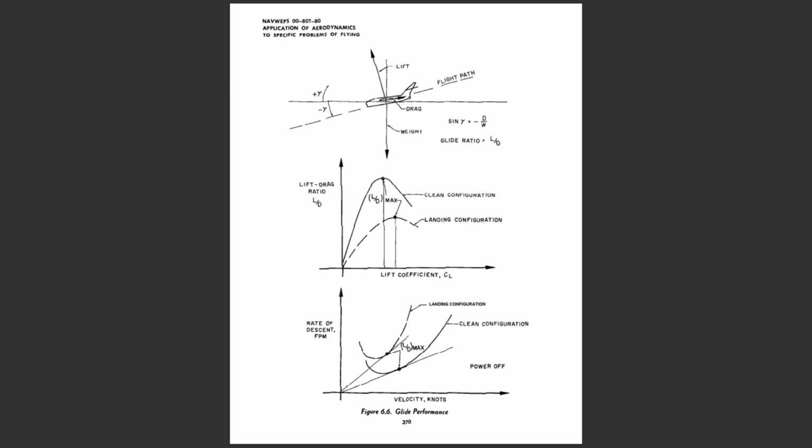While small variations in gross weight may produce a measurable change in best glide speed, the airplane can tolerate small deviations from the optimum CL without significant change in L/D and glide ratio. For this reason, a standard, single value of glide speed may be specified for a small range of gross weights at which glide performance can be of importance. A gross weight which is considerably different from the normal range will require a modification of best glide speed to maintain the maximum glide ratio.